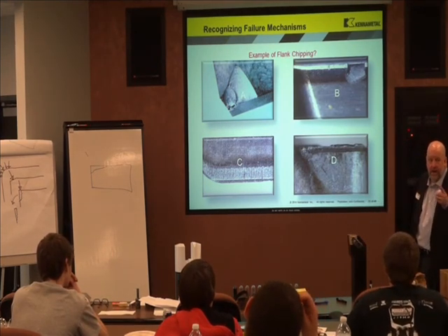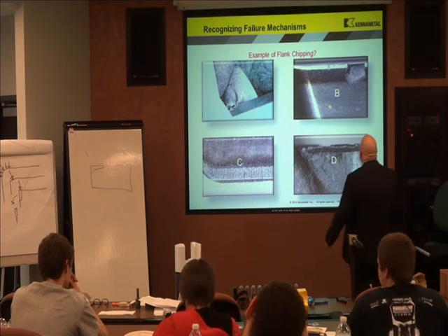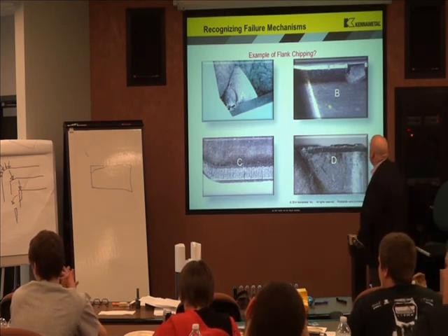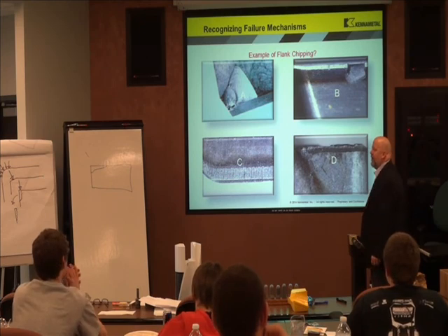Does it make sense how one can end up as something else? You got flank wear, then thermal cracking, then chipping. There's not that much flank wear. Is there flank wear? There's a little.